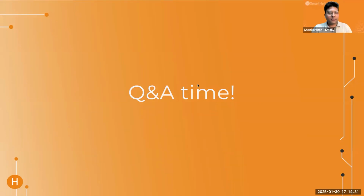Okay, I'm back. I would not say that historical data doesn't help, even in classification. There are certain issues that need a longer duration of data. Let's talk about soiling. If you give us historical data, it helps because I can establish trends, such as whenever it rained and it was enough rain to cause a cleaning impact. Those become my benchmarks to measure the soiling rate. Then even with 1 month of live data, I would be faster and more accurately able to tell you that there is soiling.